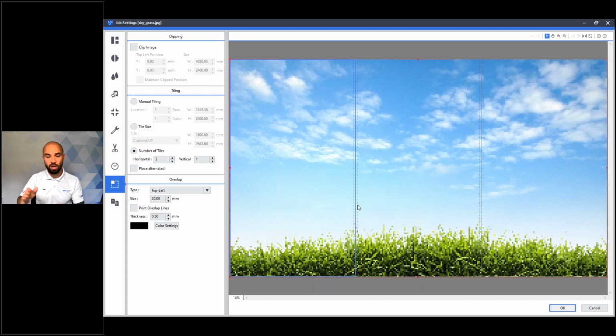So where the join is, if you can see my hands on the screen there, where the overlap sits on top of a tile, you won't see it as much. Where the sort of raised edge lip is, you will tend to see it a tiny bit. So when people walk into the room, or the direction of traffic within the room, you want to make sure that the overlap join faces that part of the room, if that makes sense.